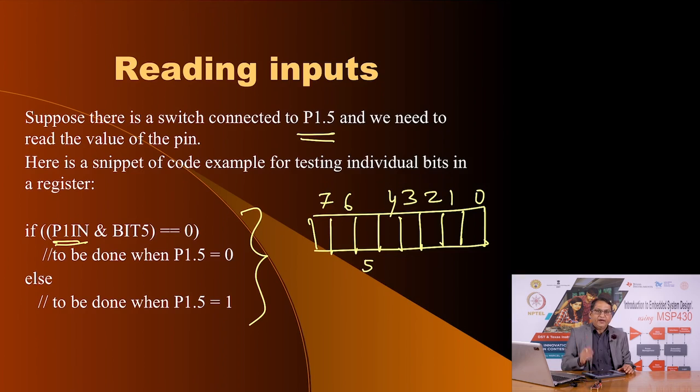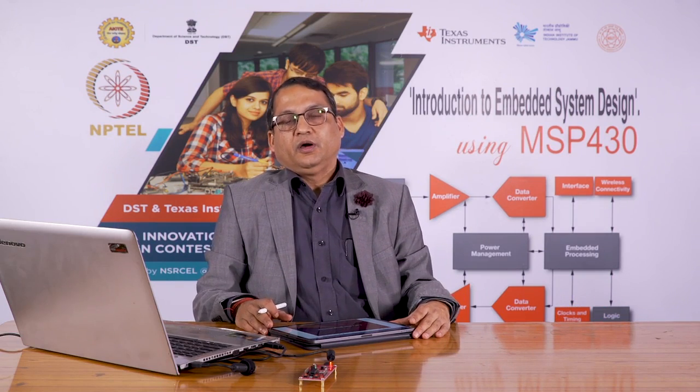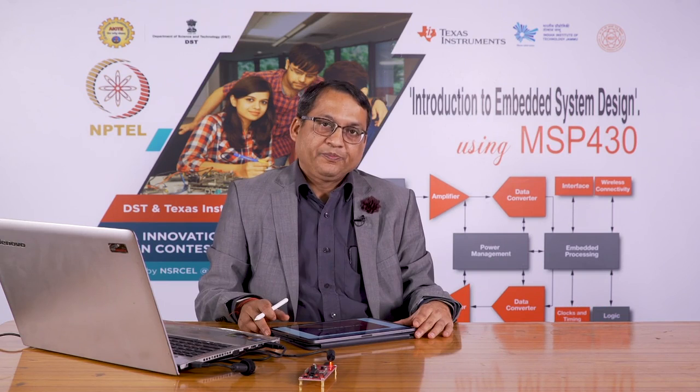So, you can read the entire register P1 in, isolate a particular bit that you are interested in using bit operations, and the result will be 1 or 0, which will allow you to do one or the other thing that you want to do. Okay. So, we have now seen how to manipulate the registers to program the MSP 430 appropriately, so that we can control the pins whether they are input or output.